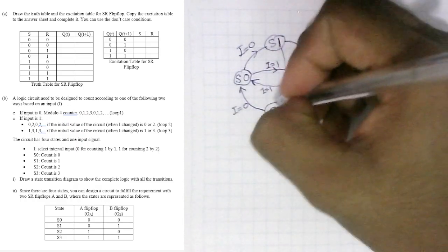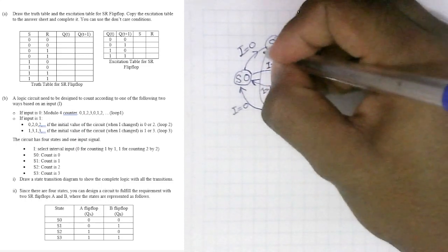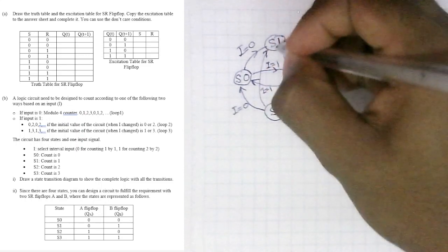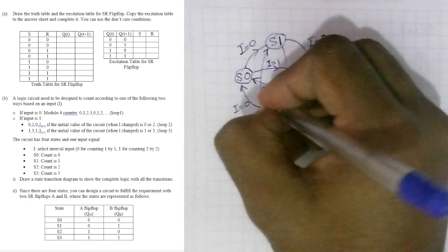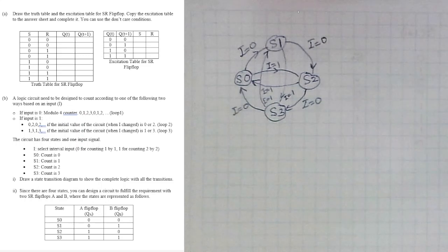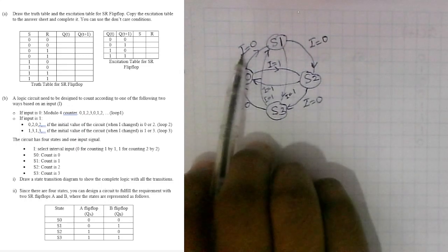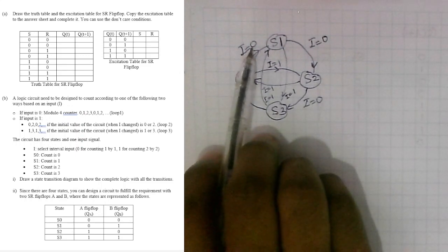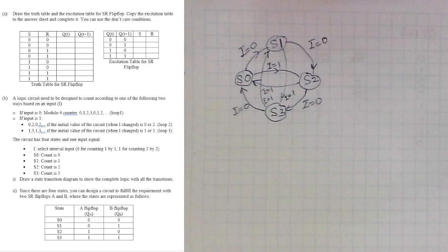So yeah, a little bit difficult, right? But let's try. Okay, it will be going to 1, right? 3 0 1. So this is also I equals 1. So this is our state transition diagram. In S0 also, double check, we can have the I equals 0 transition and the I equals 1 transition. So we have all the possible transitions covered now.